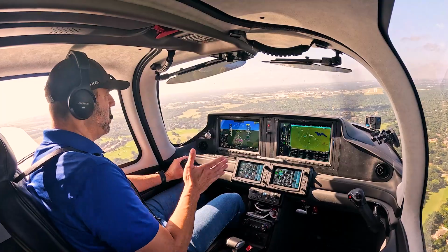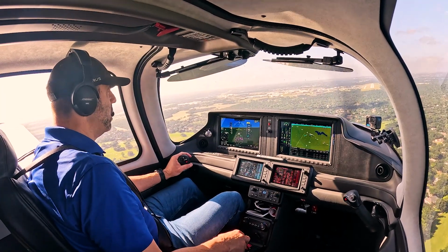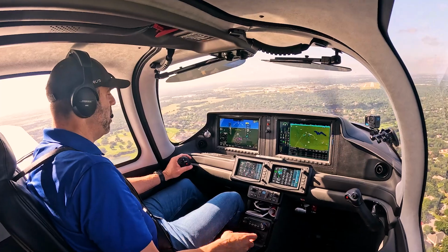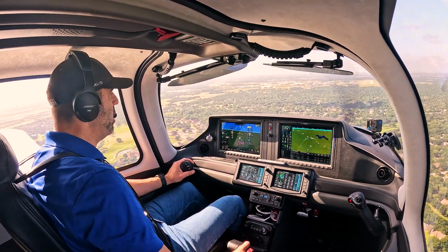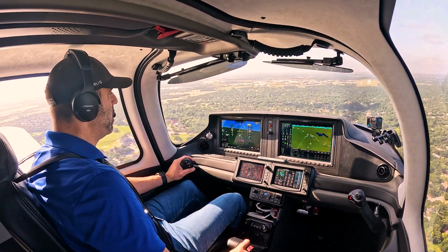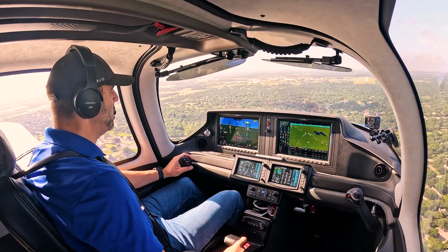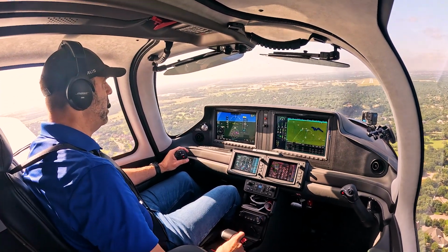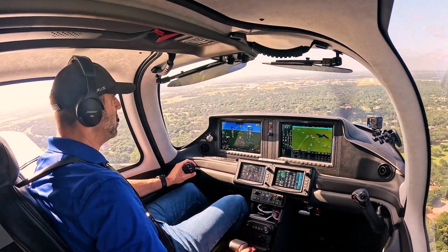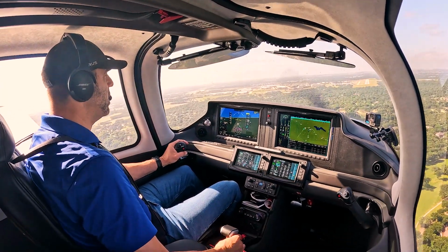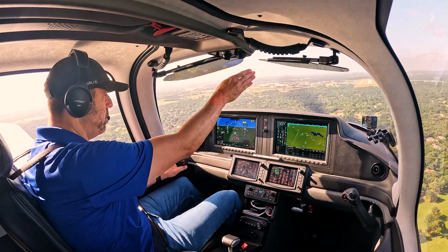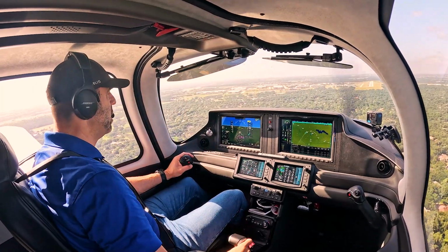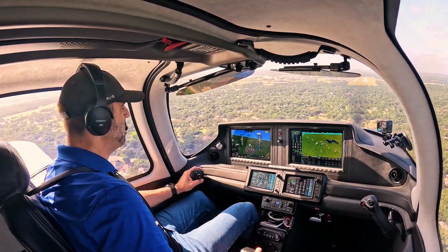So I'm using the ailerons to turn into the wind, a little right aileron, and a little bit of rudder to stay coordinated. And I'm doing whatever I need to do to keep this plane tracking on center line. Now my nose is not tracking the center line. My nose is pointed that way and the runway's over here. But as long as we're tracking right down that center line, we're good.